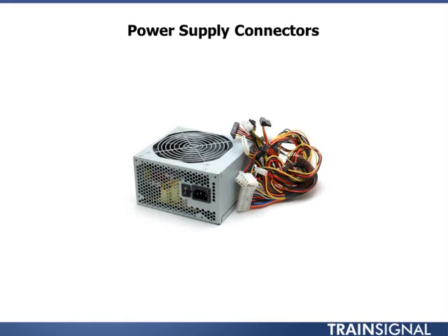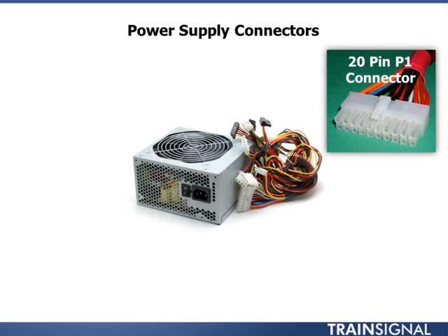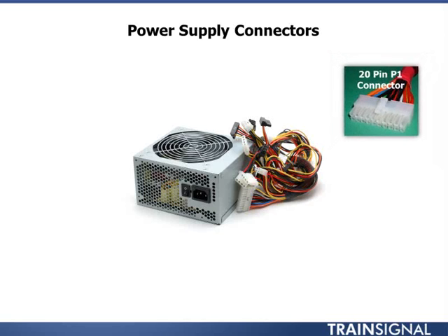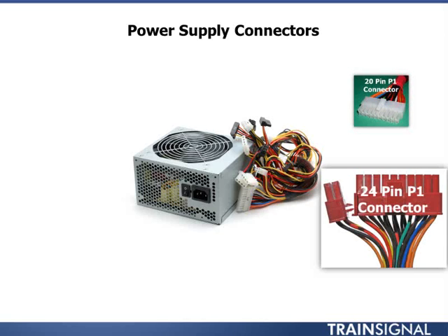But let's talk about the different types of connectors. First, you have the P1, the 20-pin connector that you remember seeing on our motherboard. This is actually pictured here. It's keyed, you'll notice, so it can only go in one way. There's also a 24-pin P1 connector, and essentially what you see out there on the left was the connector that I had mentioned that I didn't have on that particular power supply that caused me all the problems. That's your P4 connector right there.